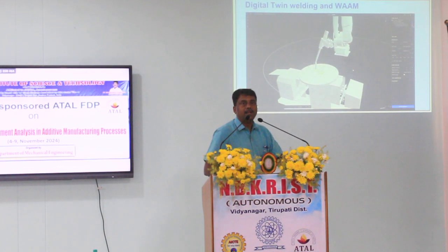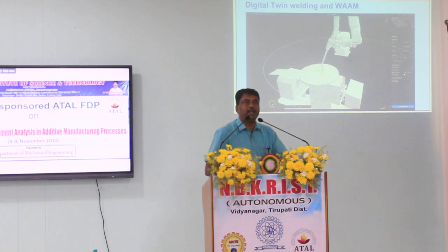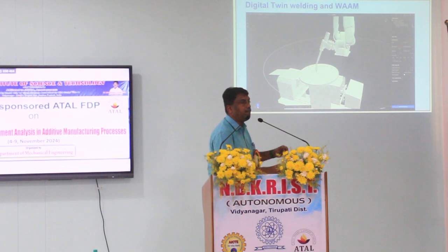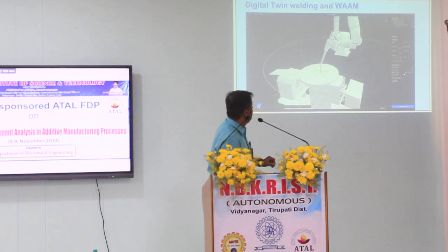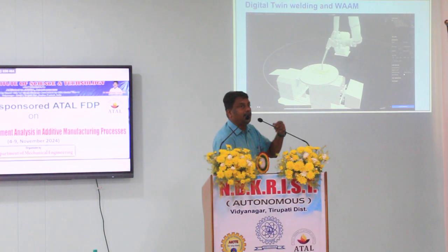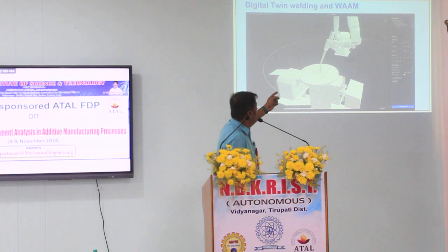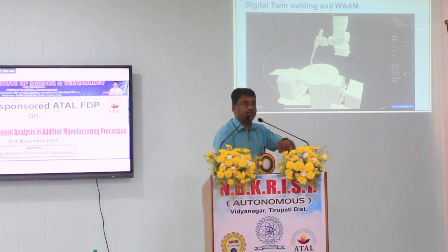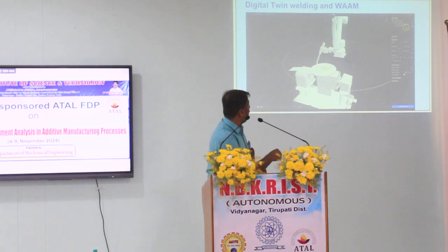was made by one of my PhD students, in collaboration with my friends in Europe, where we have a complete replica, a twin of what we have in the lab. Subsequently, we generate the required paths based on the optimization. The paths are given and each path is loaded onto the robot controller, and the robot controller will also control the welding process to get the required currents and gas flow rates, so that the part can be printed as we go.